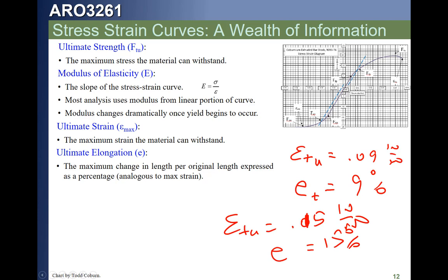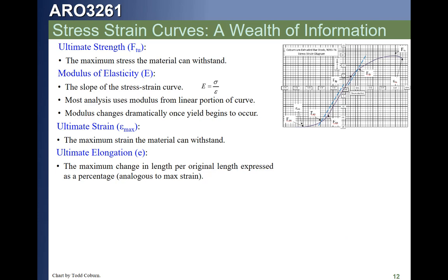The reason elongation is important for us is because there's sometimes we're going to need the ultimate maximum strain, and yet we don't have anywhere to find it. But we're going to find out in our appendix that the elongation is shown, and we can take the maximum ultimate strain as just the elongation. This ultimate strain here is shown as a maximum value, but we generally are saying that it's the ultimate strain. Also, you could call it the max strain or the ultimate strain, same thing.